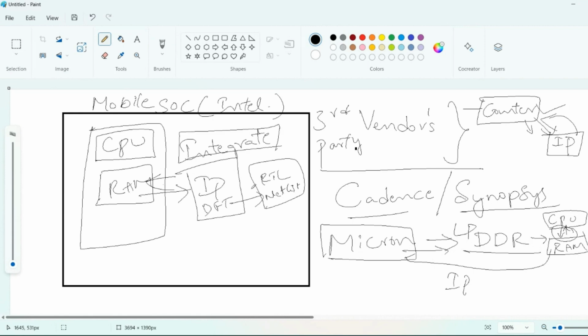The EDA tools will support integration of your IPs. Now, I'm just explaining what an IP is. There are two types of IPs: one is soft IP, the other is hard IP. Soft IP is a code, a Verilog code of, say, a 30-bit or a 16-bit counter, which is efficient, taken from some third party.